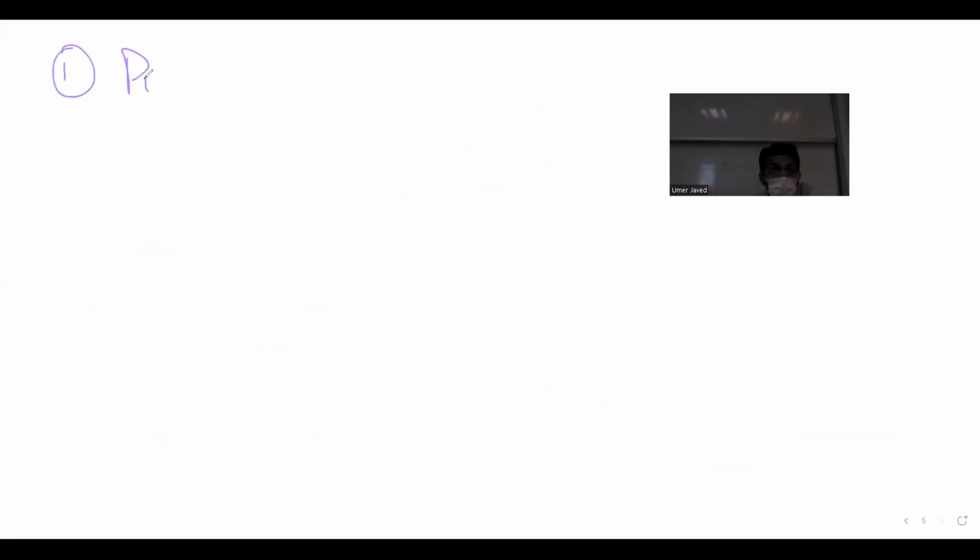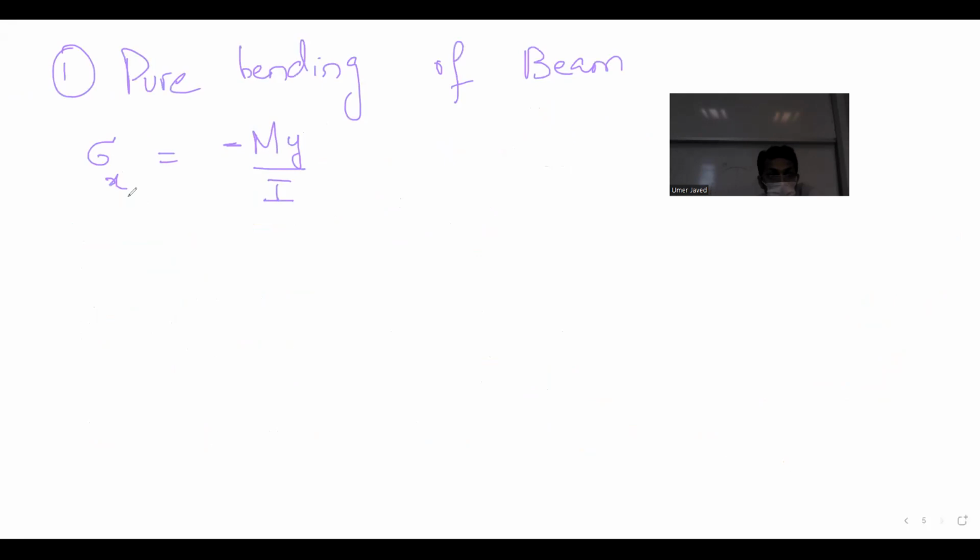Number one, pure bending of beams. Stress is equal to minus My over I. Neutral axis goes through centroid.